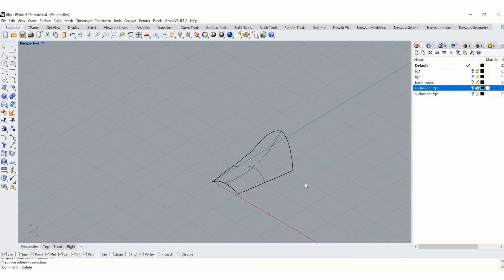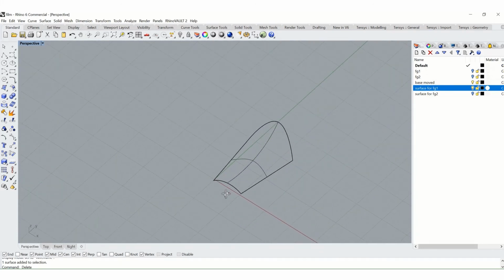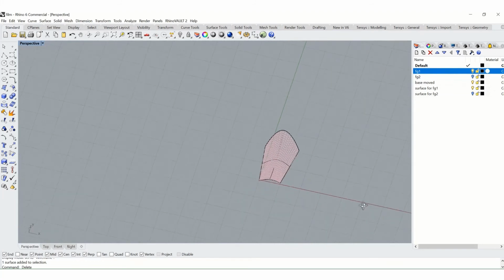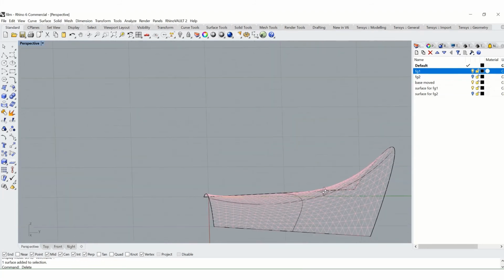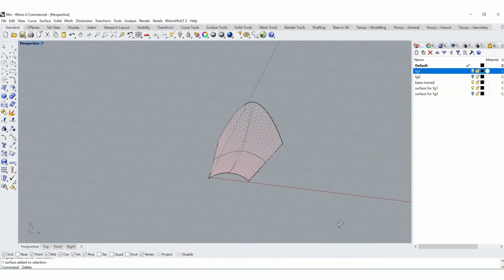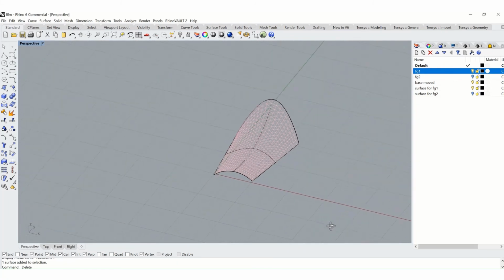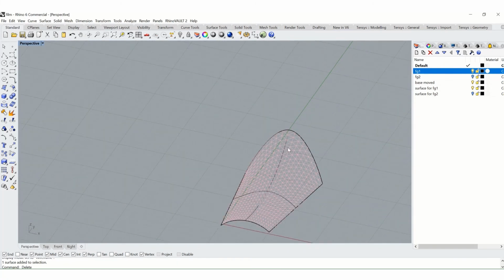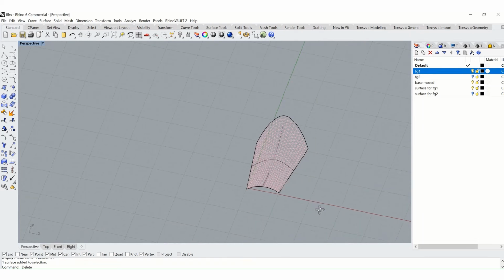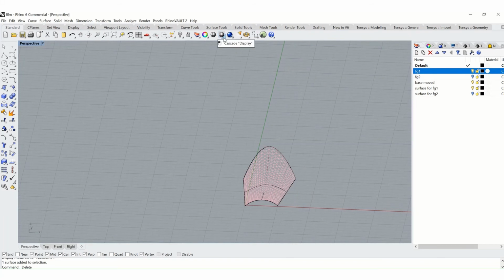And now we can compare this one with the solution given by a dynamic relaxation solver, the best on this planet, which is inTENS by Tensys. And what this would provide is this shape, and we can see that they match really well. The elevation profile is almost perfect, and the shape it has generated is really good. Bear in mind that because of the spline nature of our surface, the accuracy with only 6 internal nodes is not that bad, and it has generated a reasonably close 3D shape.